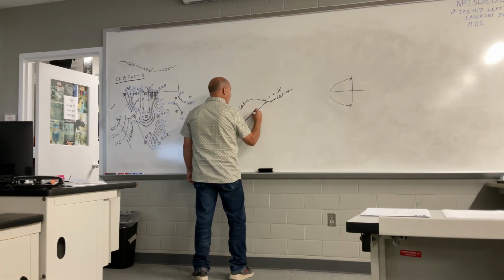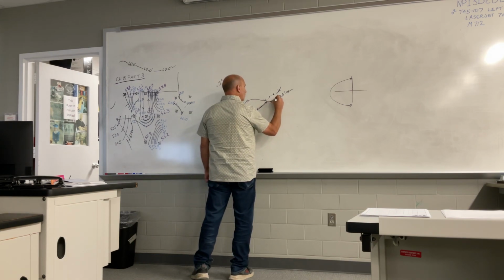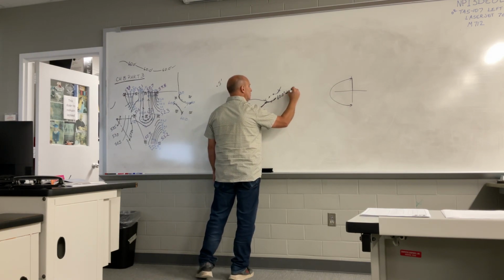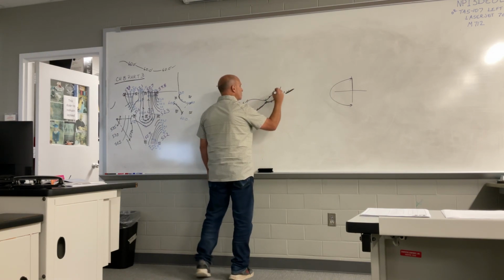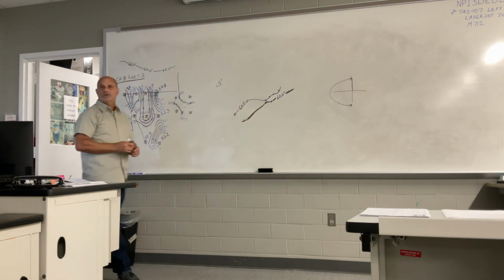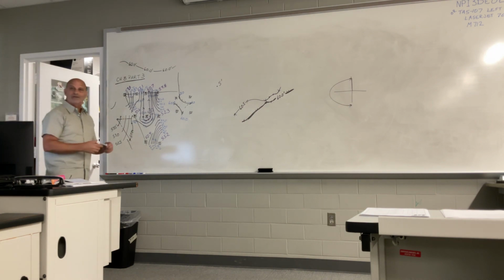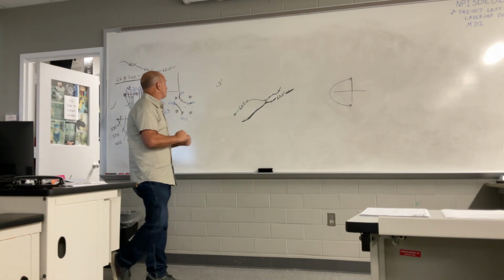So all of your point zeros are going to be in your index contour layer. They're going to be a little bit heavier line weight versus the intermediate contour. So the 0.0 is your index, the 0.5 is your intermediate, the thinner line weight.